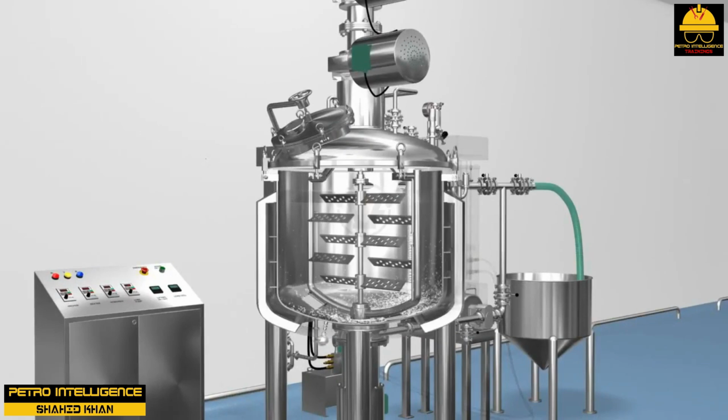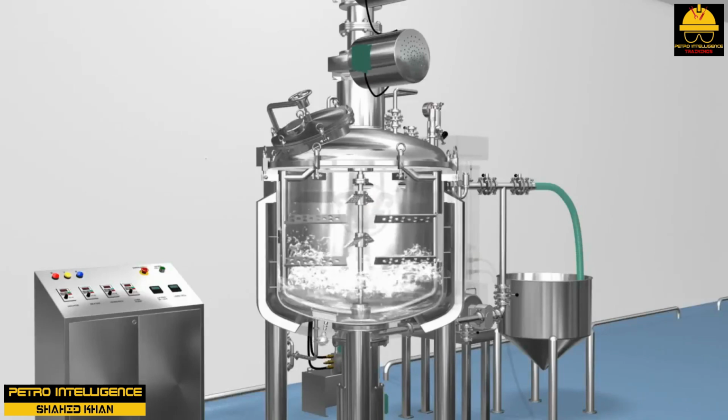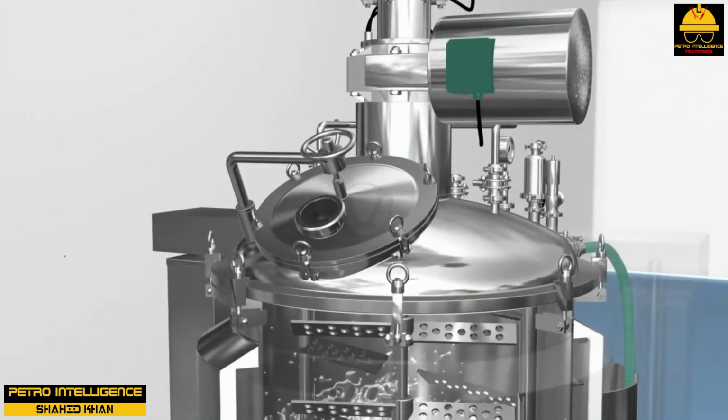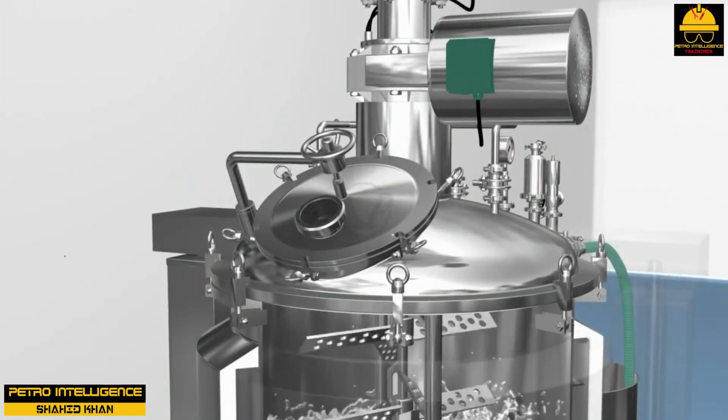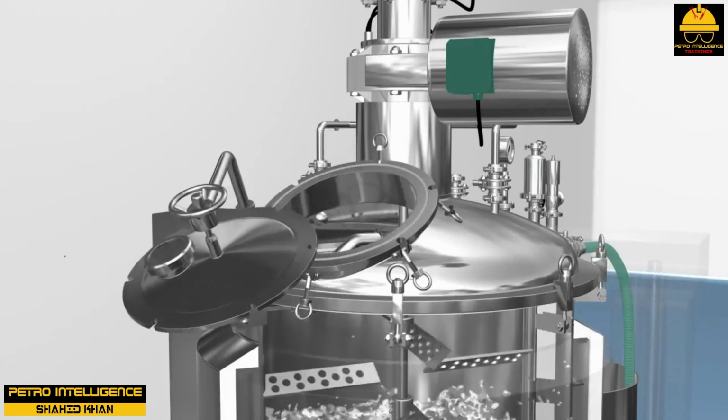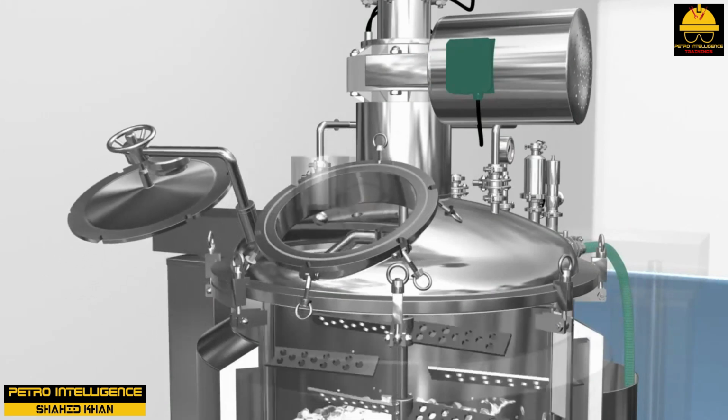A stirred tank reactor is often referred to as an autoclave or batch reactor. This type of reactor is used in both batch processes, such as the suspension vinyl resins unit and the phenolic resins unit, and continuous feed processes, such as the solvent vinyl resins unit and the polyethylene unit. The basic features of a stirred reactor are designed to provide long reaction times, mechanical agitation, and a method of cooling or heating the reaction.